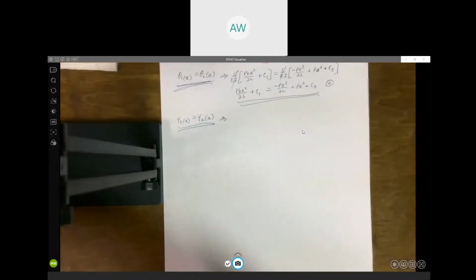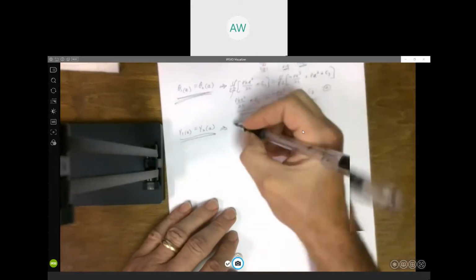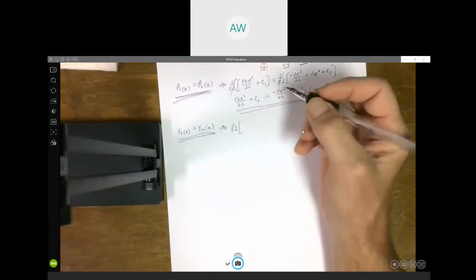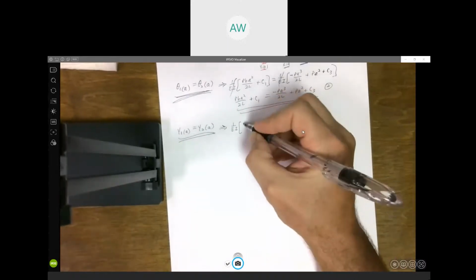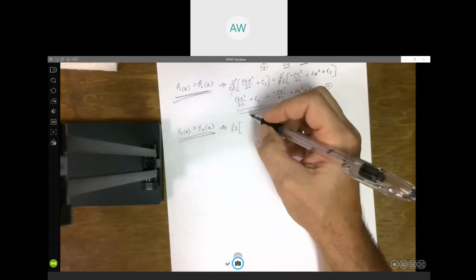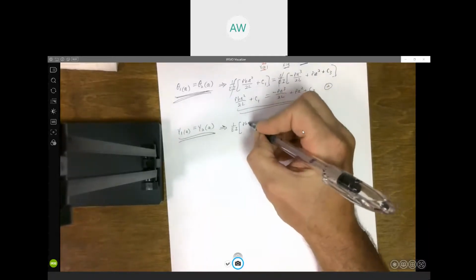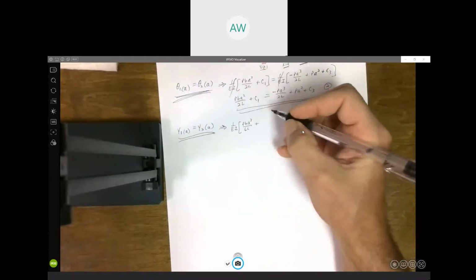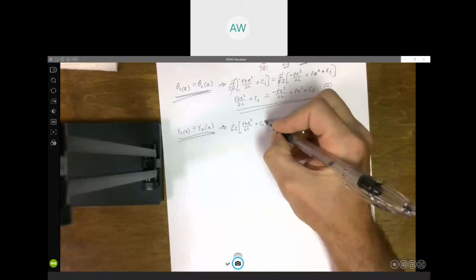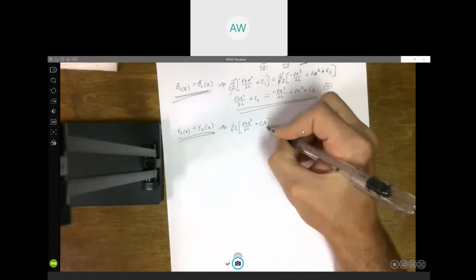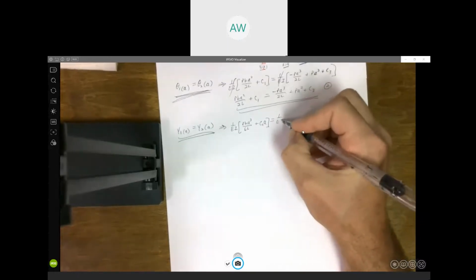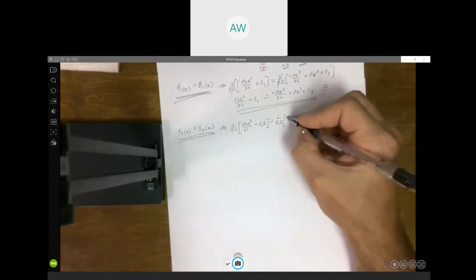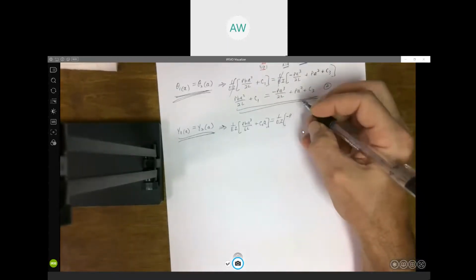So that's what we're doing. Write this down. We're going to get 1 over EI. Plugging a in for x into that y equation, since it's PBx cubed, I'm going to get PBa cubed over 6L plus C1 times x, so that'd be C1 times a. That's equal to 1 over EI, plugging a in for x into y2, I get minus Pa times a cubed.